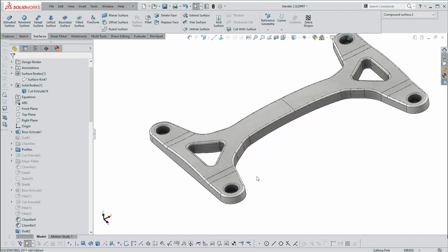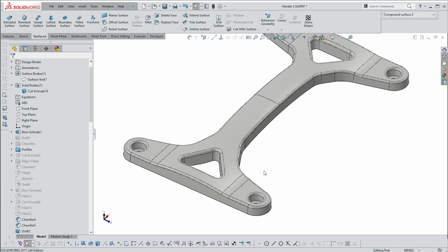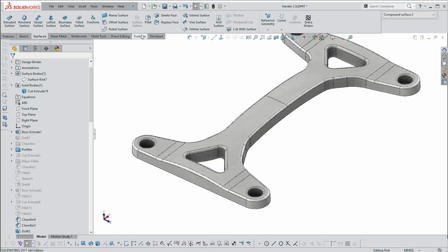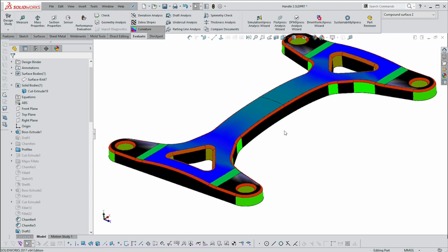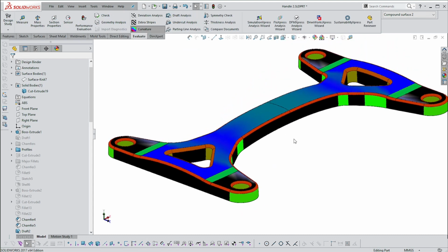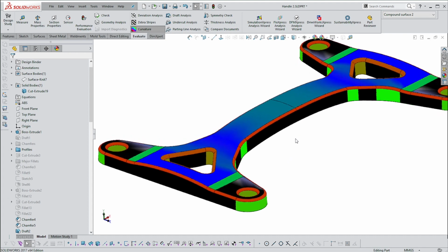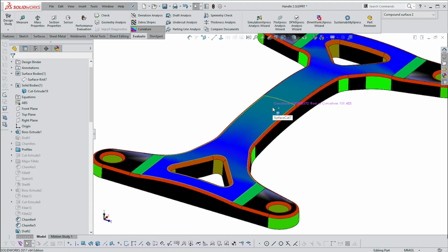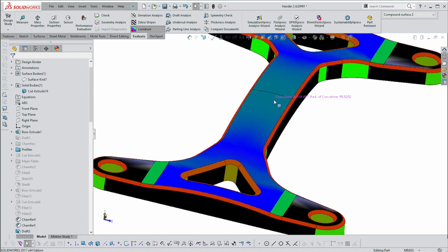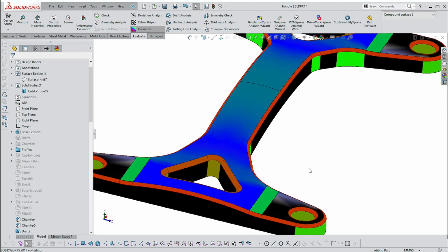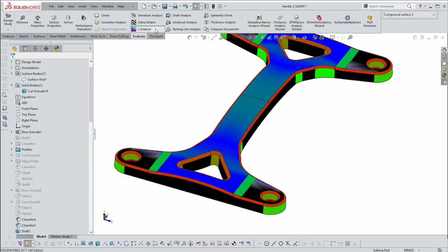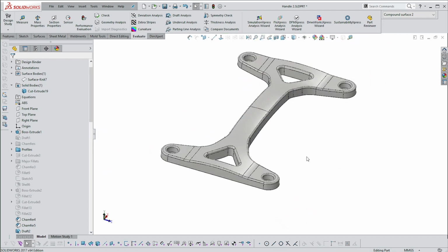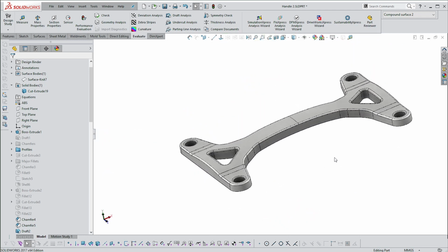One way to check to see that you are getting what you are looking for is to do an evaluate. So go to curvature, and all of the solid colors are regular geometric features. All of the ones with shade are not. So in this case, that surface is not regular. You can see it's shading from gray to blue. And this one here, the one that I want to be flat, is not flat because it's shading from blue to black. So that's a good way of just making sure that you don't waste time in your drawing doing what I did.